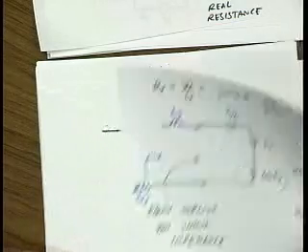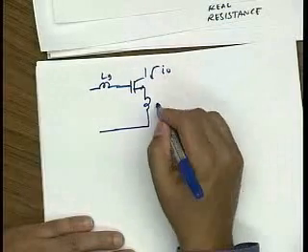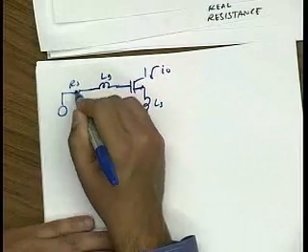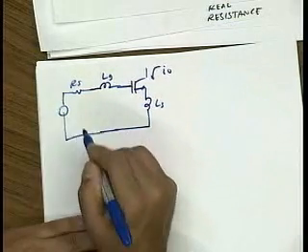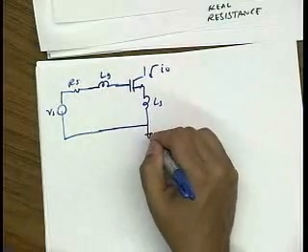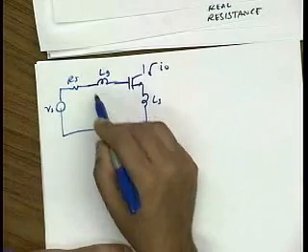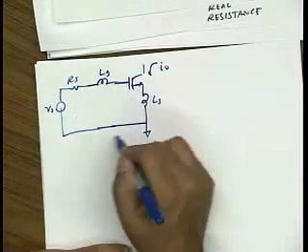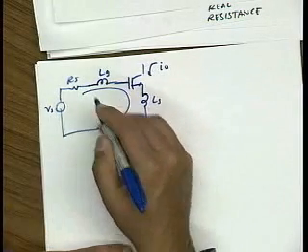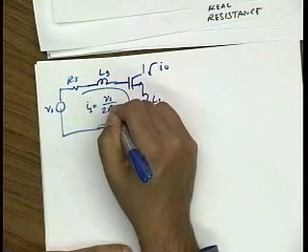Okay, so let me calculate the current gain under those conditions. So this is LG, this is LS, and then I hook up RS here, and this is VS. And I want to find the current gain of this circuit. Okay. So notice that by placing LG here, I've actually put my circuit in resonance, right? So the input current, IS, is simply VS over 2 times RS.